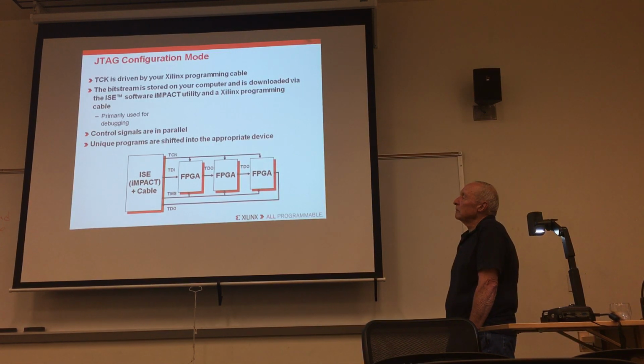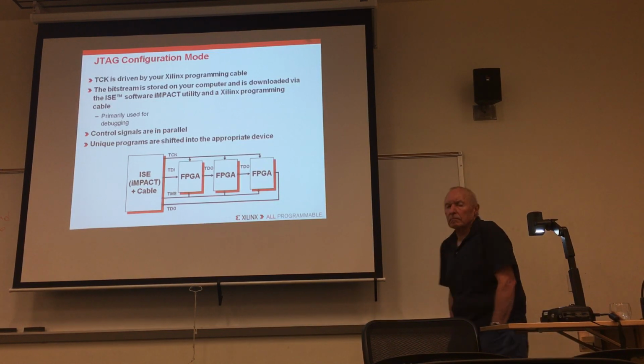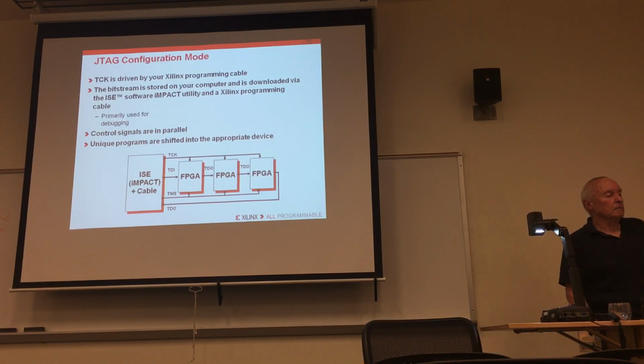Since reconfiguring in this mode does not require any memory components to store the bitstream, this mode is primarily used for debugging and not for the end use of an application. This flow is possible because Xilinx FPGAs are SRAM-based and thus reprogrammable. This means that the user only has to generate a new bitstream with the iMPACT utility and then re-download the new design into the FPGA. While Xilinx does not specify configuration times, downloading over JTAG takes between a few seconds and a couple of minutes. This is done at default cable speed with the Platform Cable USB being used. Now this will vary depending on your PC, FPGA, and, as I mentioned, the programming cable you choose.